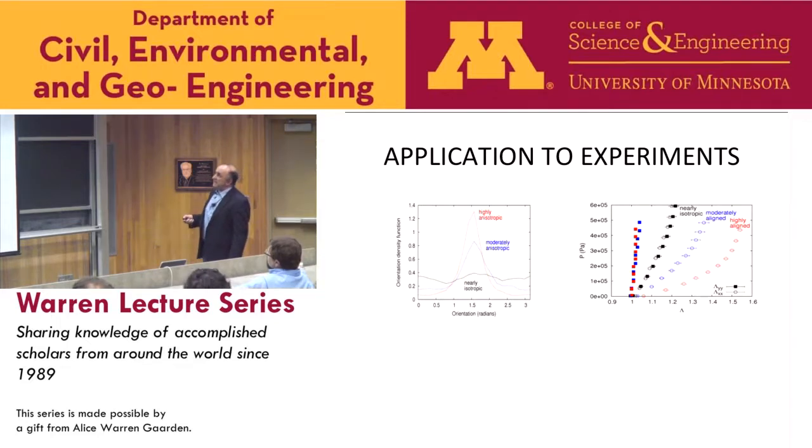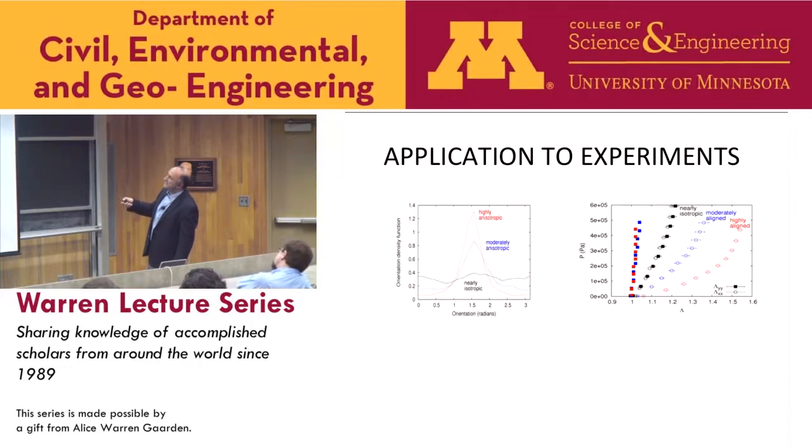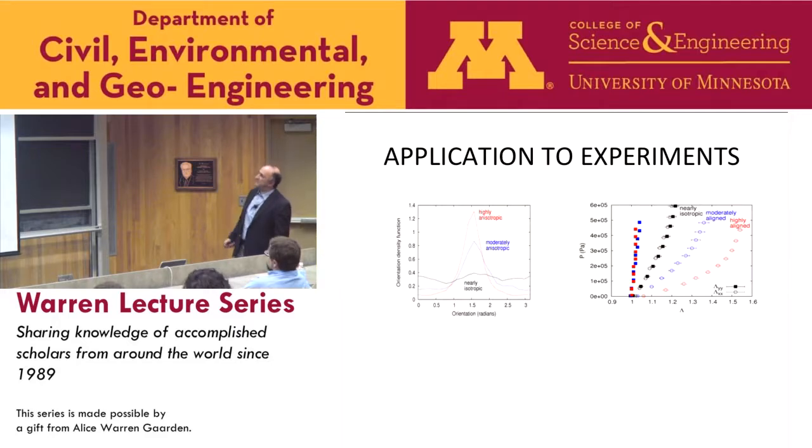Okay. So the materials produced as a result of varying speeds were subjected to biaxial tension experiments, and then you can see that for nearly isotropic, lambda x and lambda y are the same, right? But then you could see that for, let's say, highly aligned, there is a significant difference between the two stretches, right? And blue also, right? So this is experimental data.